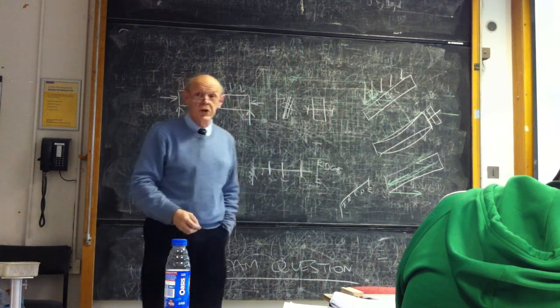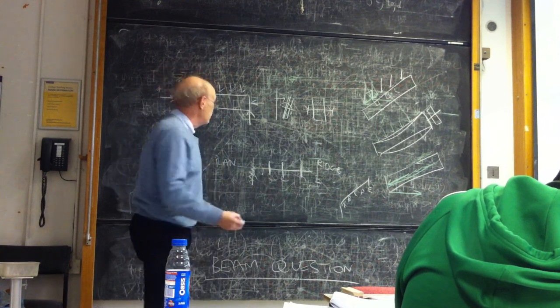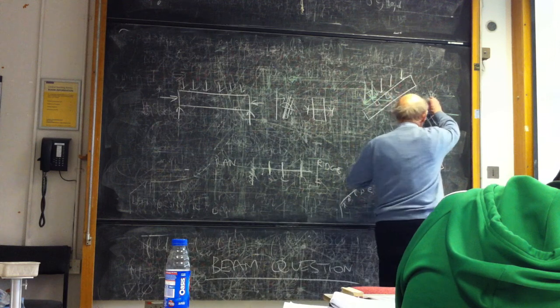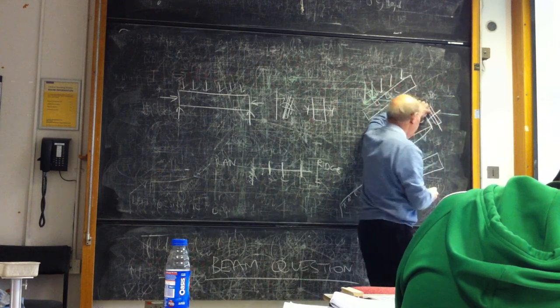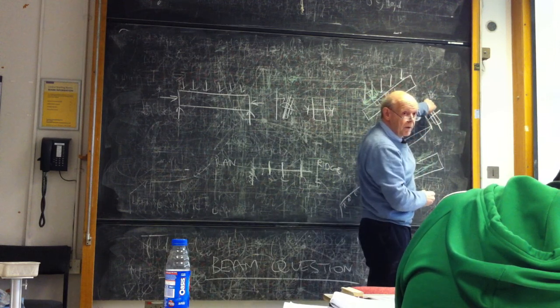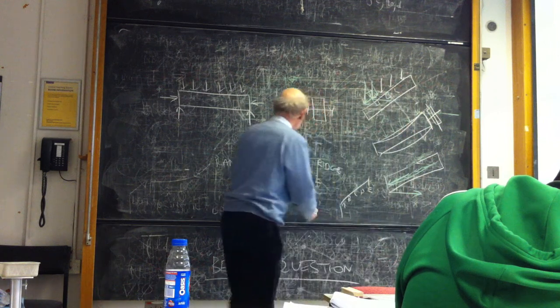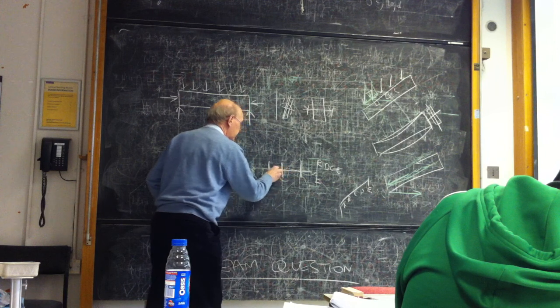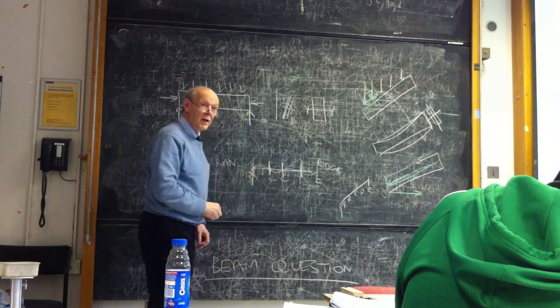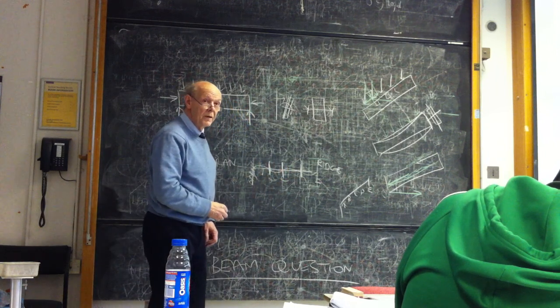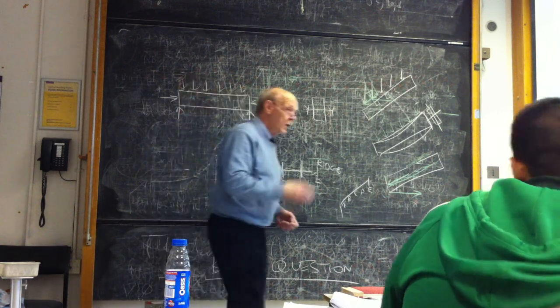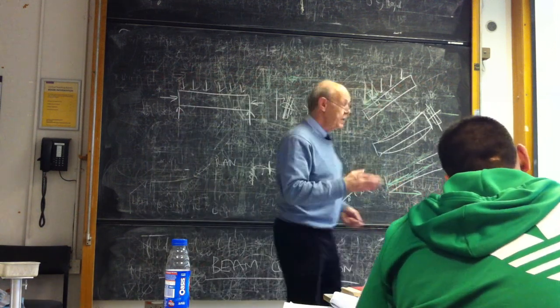And if it's going to buckle sideways like a column, then the most it can do, because don't forget, if it buckles sideways, it's going to buckle about that axis. So if it buckles sideways, because of the propping effect of these, the most it can do is buckle something like that. But when it comes to twisting, it's quite different.